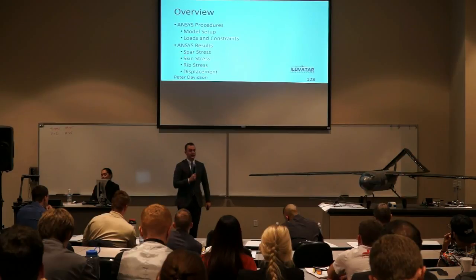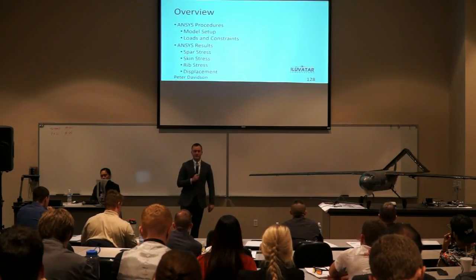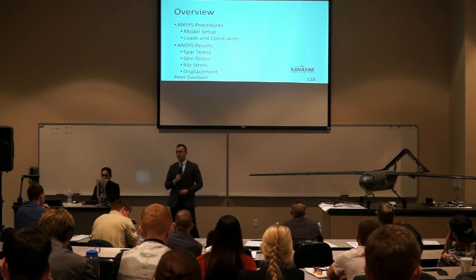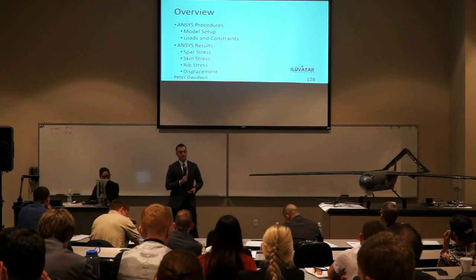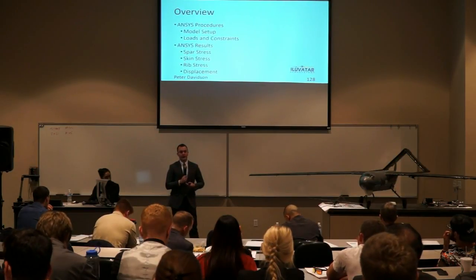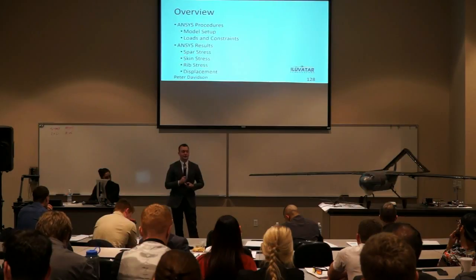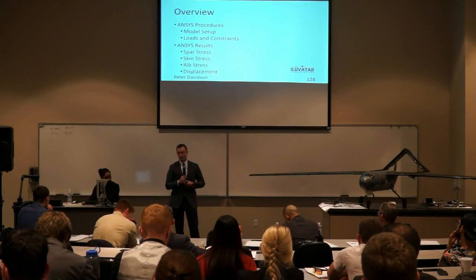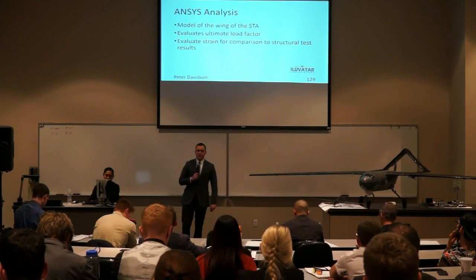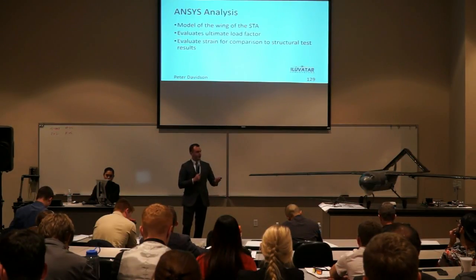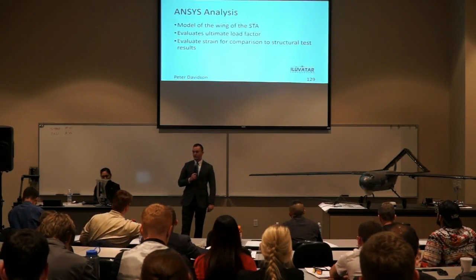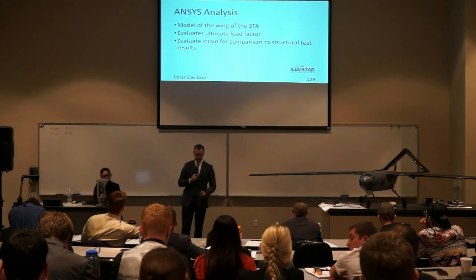The reason why the ANSYS analysis was important is because it gives us the ability to predict loads in the wing. It will be used later on when compared to strains from the structural test article, and it's also used to feed in the ultimate loads that calculate the predicted margin of safety of the flight test article. So the ANSYS is a model of the left wing of the aircraft, and it evaluates the ultimate load factor and also evaluates strain for comparison to the structural test results.